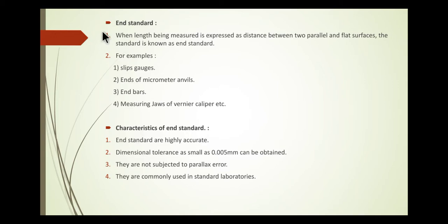Now, end standard. When the length being measured is expressed as a distance between two parallel and flat surfaces, the standard is known as an end standard. For example, slip gauges, ends of micrometer anvils, end bars, measuring jaws of vernier caliper, etc.